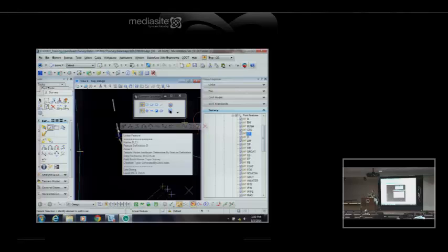I could insert a different feature and make it a chain. They didn't all have to be the same feature. In OpenRoads survey, there are 3 different types of linear features. One is a graphic linear feature. A graphic linear feature would just be something I draw in MicroStation and say, import this into the terrain model. So I could come in here and just draw a 3D line string and say, take it into the terrain model as a break line. So that's a graphic linear feature.